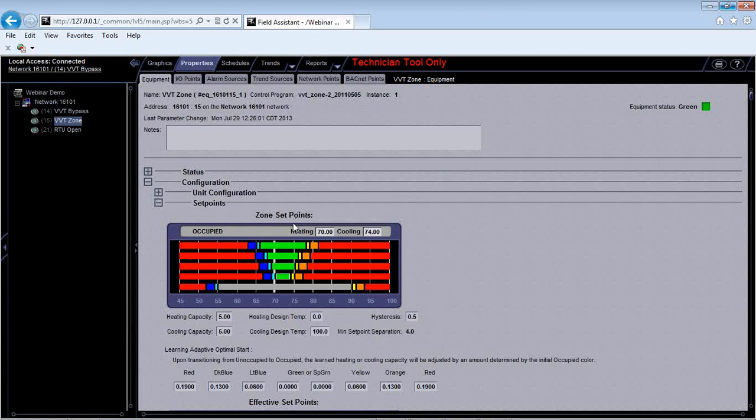Okay, so the green values down the middle are you're within your set point range, you're doing great, you're green, good to go. If you look to the right of it, you got a little yellow. That means you're getting a little warm above your set point. As you go into orange, you're getting a lot warm, and then you're finally going into red, which would be too hot and basically in an alarm status. And then it's the same going on the cold side with light blue and then dark blue and then alarm.